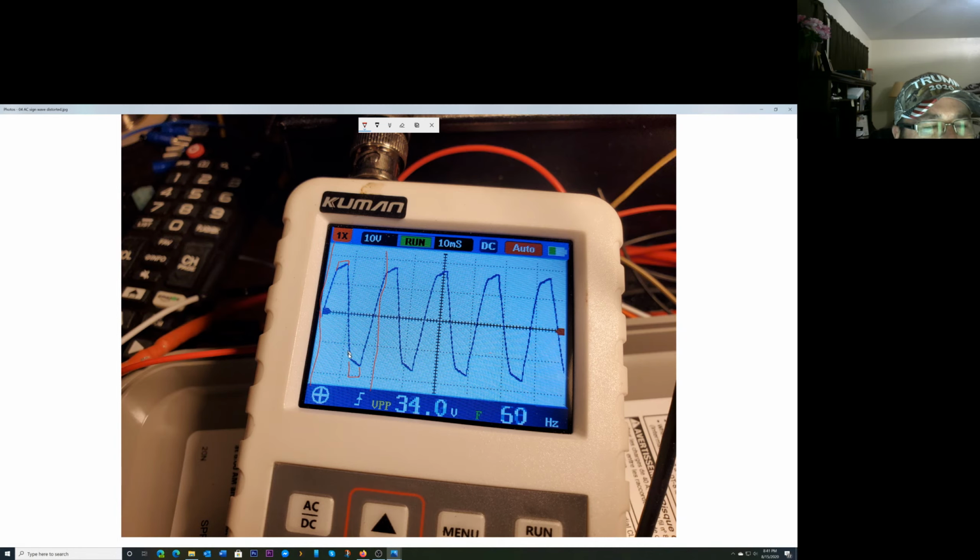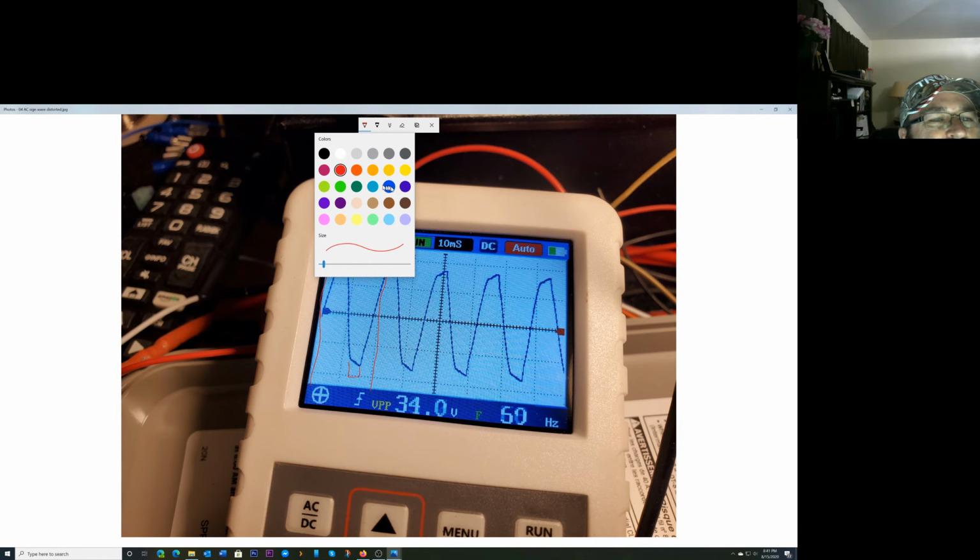This is just my sine wave, but no current is flowing because at this point my DC bus stayed up here, and it sags down, being pulled down by the motor or the compressor, until it hits here, and the sine wave was now greater than the DC bus voltage, and then boop, it started pulling current. And then the DC bus stayed up until it got down here, and it's going like this, and that's your ripple. So I should change colors actually to show the DC bus.